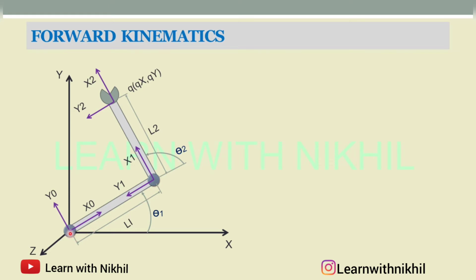I'll repeat again. If you want to find the position of this end effector, that is Qx and Qy, with respect to this base, we have to find the position of this with respect to its previous joint, and this with respect to the previous joint. Then you have to multiply both and then we'll get the coordinates of this end effector.